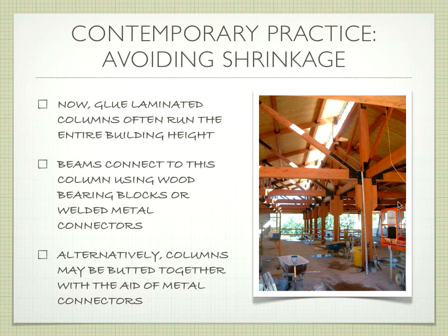The problem is it starts to get too heavy for the amount of bearing capacity that it actually has. It's not that strong in compression compared to, say, concrete or even steel. So it starts to get a little tricky. I don't have a good answer for you. I'd say you could probably go 4 stories, maybe 5, but it's a little iffy after that. It's still very similar to light frame.